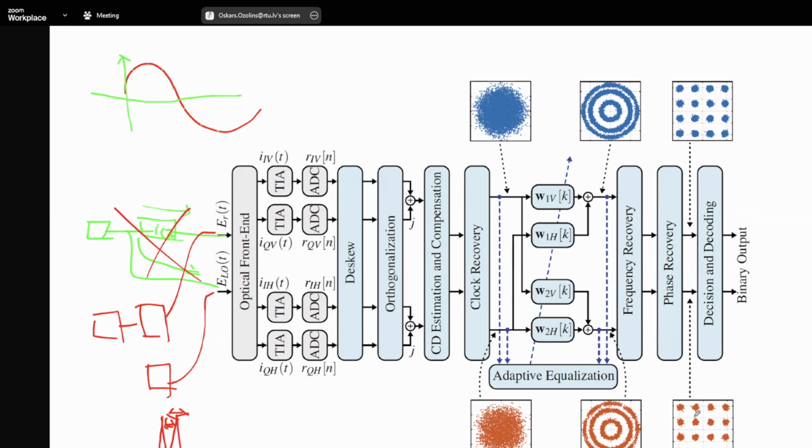And then when we have these symbols, then we need to get to bits and decisions. We need to decide, okay, this symbol is here, and we kind of put the boundaries. And these boundaries also can be done in different ways. So we just say in MATLAB, okay, points which are in these boundaries are this symbol. Then if there's some symbol here which actually belongs here, then we get an error. And then we also talk about bits and gray coding and different things.